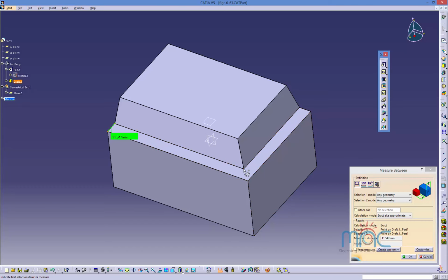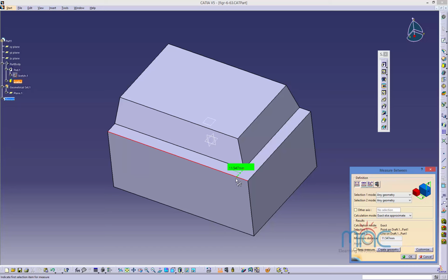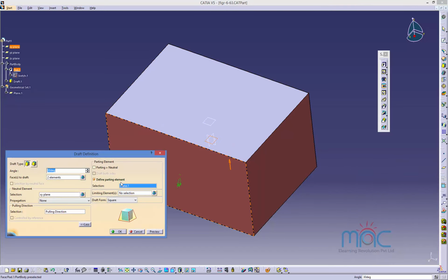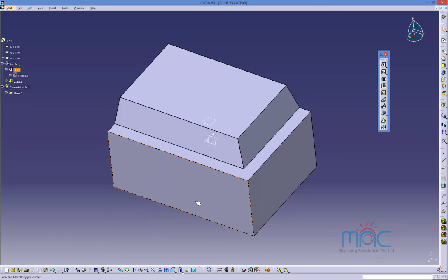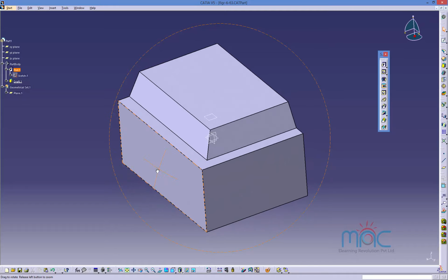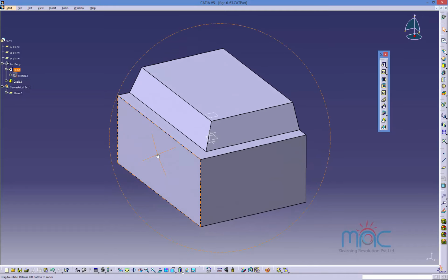And if you go for this to this distance, the same is maintained. So throughout these operations, it does not see any direction or control for your distance. So what you do is, when you select this particular parting surface, that will be guided. Later on you can trim and get the final dimensions if you require. So this is the two-stage drafting, directly by referring to a parting surface.